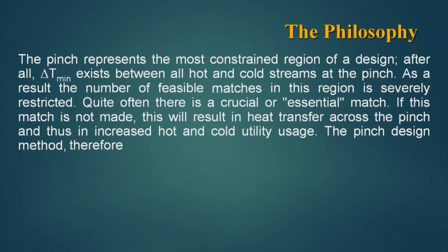Let us first see the philosophy. The pinch represents the most constrained region of a design. This is the most important fact of a pinch design procedure. After all, delta T minimum exists between all hot and cold streams at this pinch.